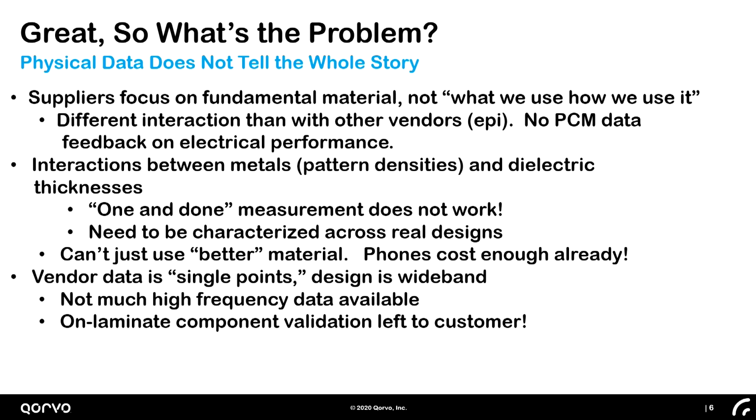Typically, the vendor data, and I'll go into this in more detail later, is usually single points. The designs are wideband, so it's not so great to have single points. And there's not a lot of high-frequency data available on the typical available laminates that we have right now, and I'll show some things on that in a little bit.